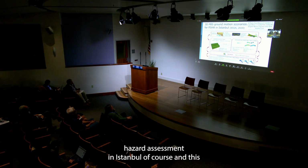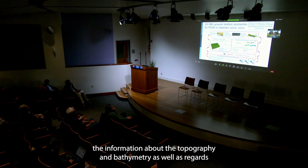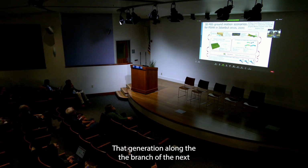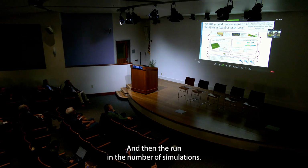Of course, all of you that are familiar with the construction of a numerical model for such physics-based simulations know that it is very demanding, not that much in terms of computer time, but especially in collecting the information about topography and bathymetry as well as regards the Marmara Sea, the tectonic context for the fault simulation, the geology and geotechnical characterization of the area, the generation along the branch of the North Anatolian Fault on the Marmara Sea that these simulations refer to, the generation of a sufficient number of slip distribution models, and then running the number of simulations.